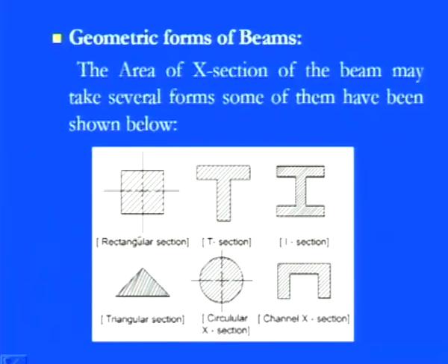If you want to design for the distribution of bending stresses, or see how shearing takes place, you can simply see that the neutral axis is well defined. You can define this neutral axis and the region of these bending stresses whenever we have a rectangular cross section, and you need to choose the effective dimensions to calculate the effective area. So this is one cross section of a beam, a rectangle. We can also choose the T section, where we simply remove material, so that once you remove the material you have less inertia because the mass is removed.